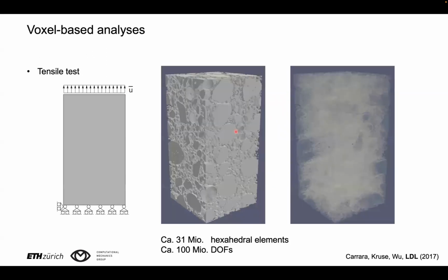So this solved the issue of contrast, and we could finally carry out voxel-based analysis on concrete specimens taken from the tomograph. So these are, again, the videos that I started with a few slides ago, and now I can tell you that this is real concrete added with barites and 2.6%, where we segmented pores, cement matrix, aggregates, and we started by studying a tensile test on this specimen, and the results are the cracks that I've been showing you already before.